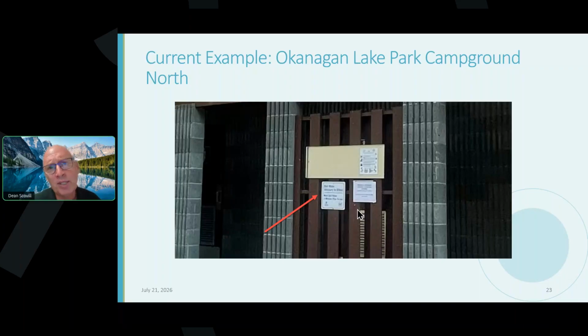I didn't have enough time to dig into the records here at the campground and look at, in terms of the reservoir, how deep the well is. There is no treatment, I know, on the system. But is there a case to put treatment on, maybe look at the reservoir, and ask whether there are areas we can improve on? Maybe there's some infiltration coming in for potential contamination into the reservoir. The reason I'm saying reservoir, I don't know for a fact, is that from my many inspections, the weak point was the storage. It wasn't so much the pumping, it was the storage. Could be the well too. Those are the two vulnerabilities right there.